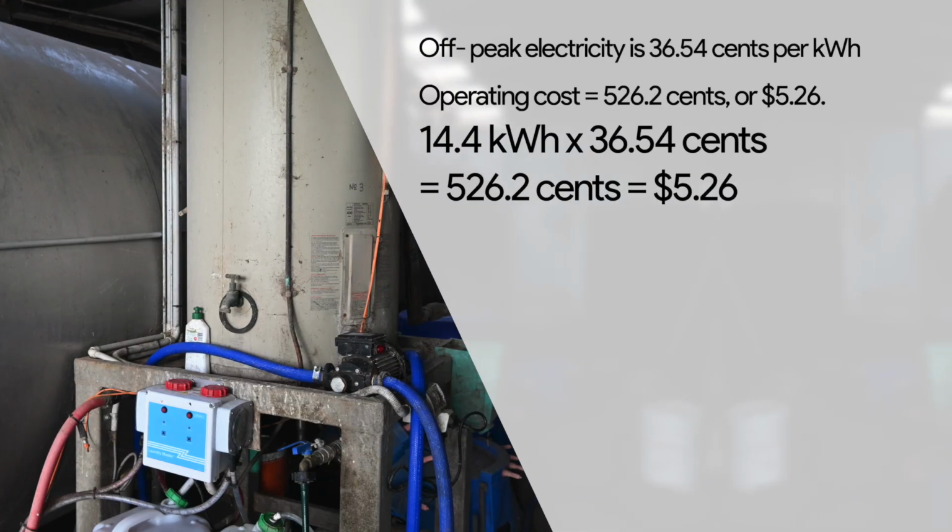Therefore, the cost of operating this hot water service would be 526.2 cents or $5.26. 14.4 kilowatt hours times 36.54 cents equals 526.2 cents or $5.26. Let's summarise.